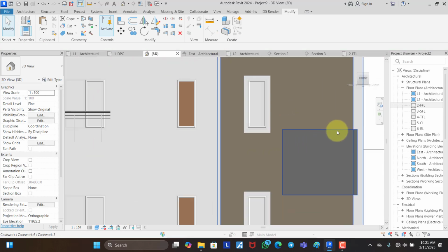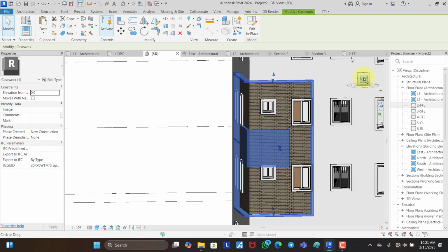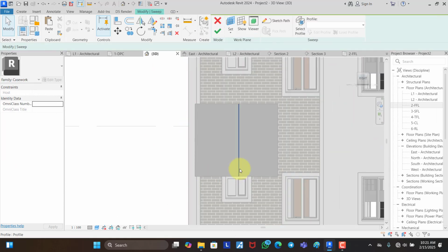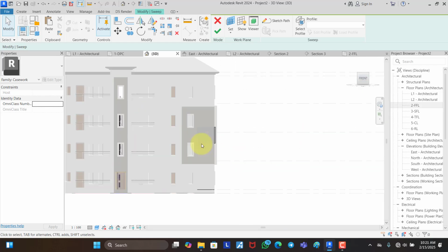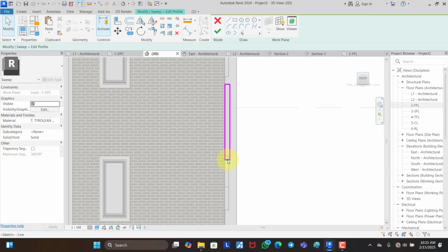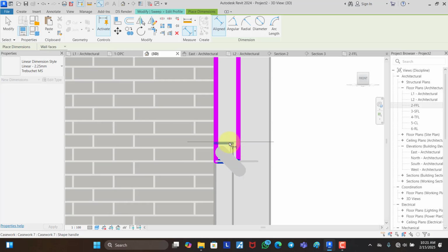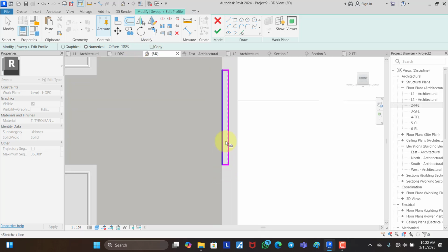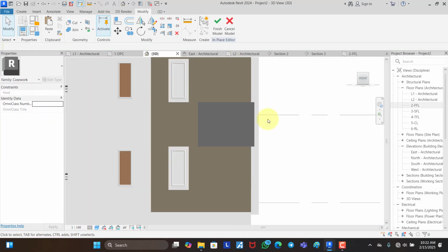And we also do the same thing here. This one doesn't, it's not touching. Okay, it's touching somewhere here. So we edit it from this point. Because we want to make sure everything is equal, let's dimension this first of all. 100 mm. So we're going to be taking an offset of 100 mm without copy here, and also down. All right, good. So this is what we have here.